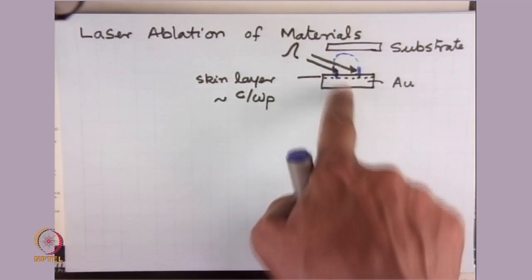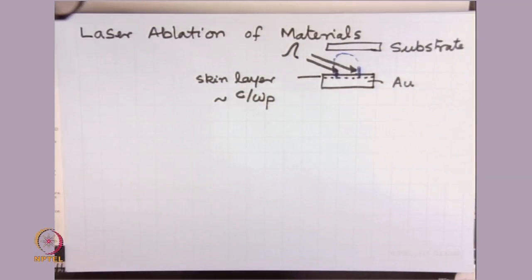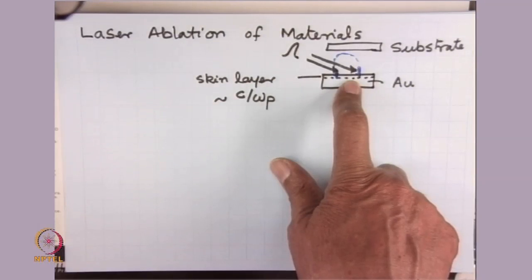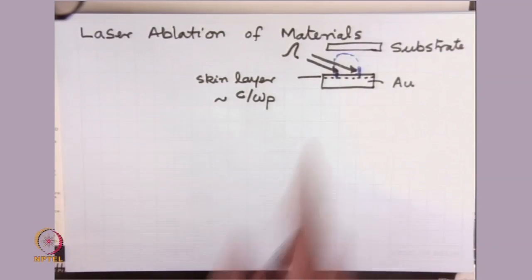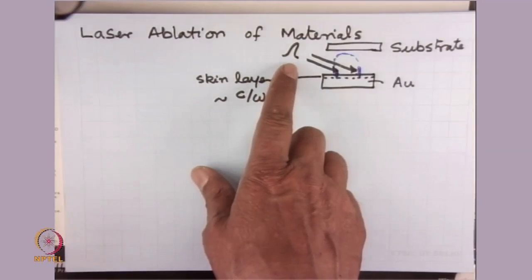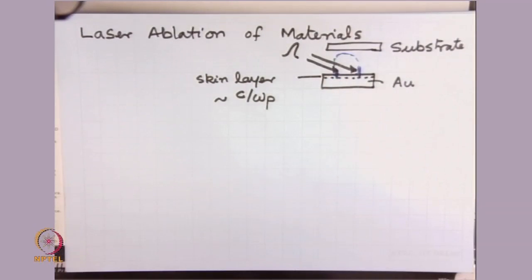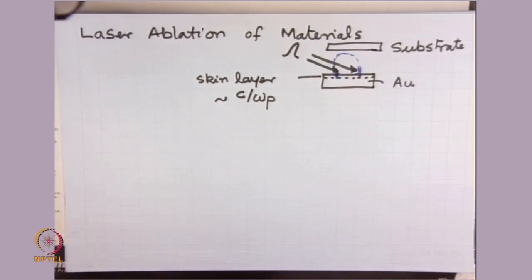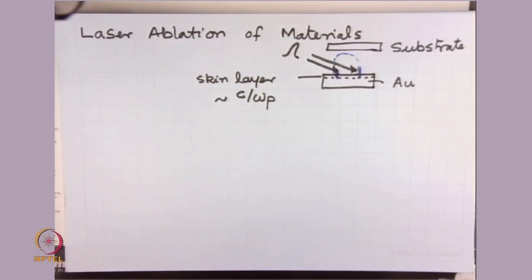And secondly, the heating rate depends on the laser intensity, so it is limited by the laser intensity. If you do not have a very, very powerful laser, then the heating rate is slow, and the heat that is generated here can be thermally conducted out downwards. So either you should choose a very large intensity laser, and you should choose a larger cross sectional area of the laser shining on the gold surface, then you can deposit a large surface area film.